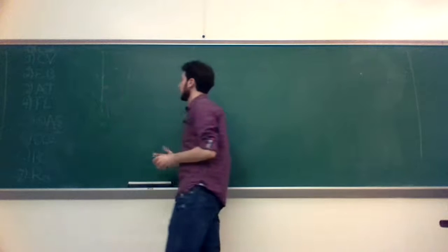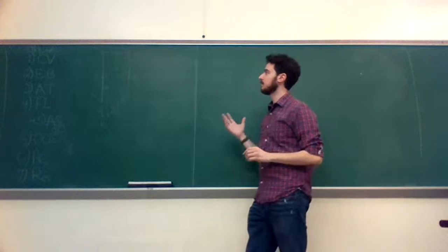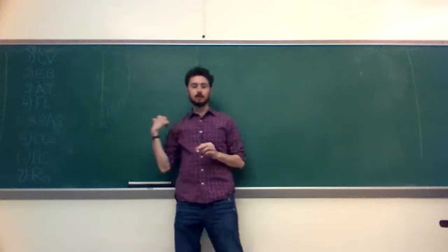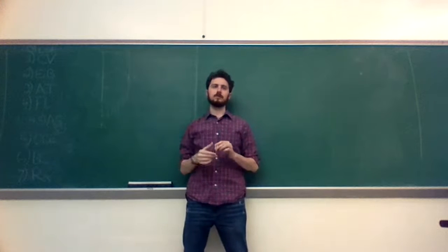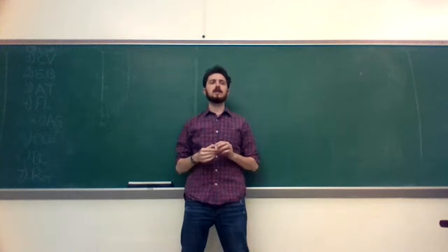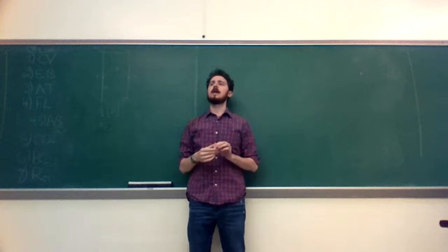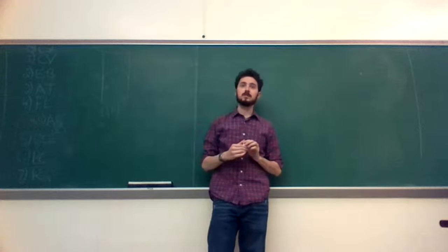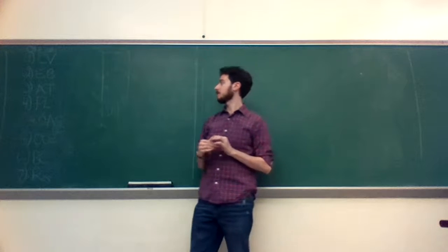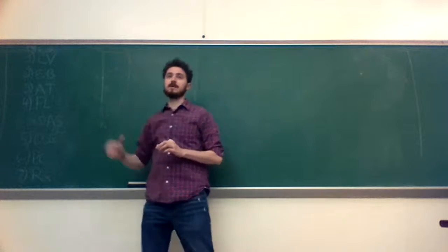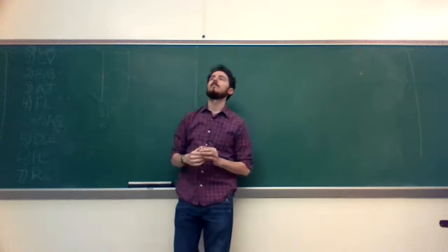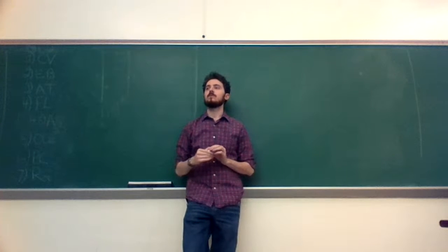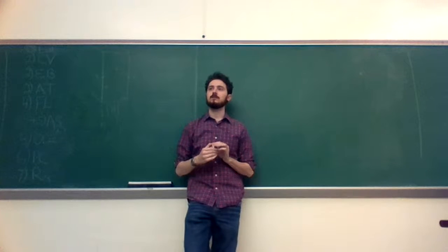Oh, so now there's a little simplification. This is all still prologue. This is before we get to the control volume. Because it's symmetric, we can do something else to simplify the problem. It's going to help us a lot in step 6. We get the boundary conditions. Right now the boundary conditions are constant surface temperature at both sides. We're going to make a simplification now that's going to help us later. We're going to have an insulated boundary condition.